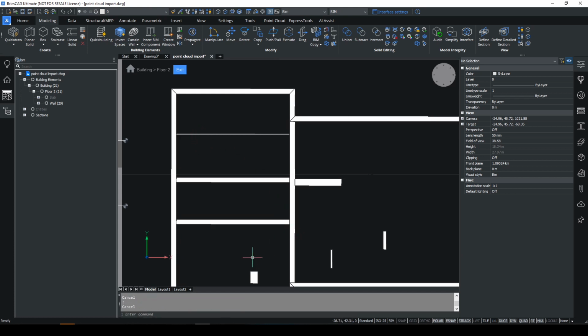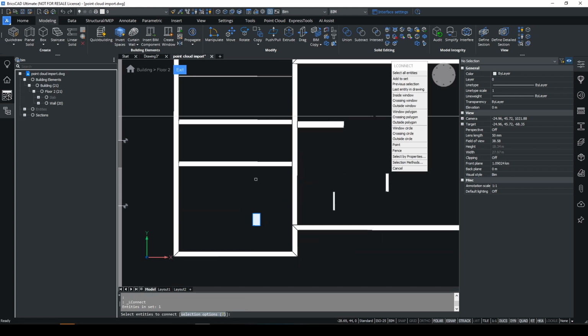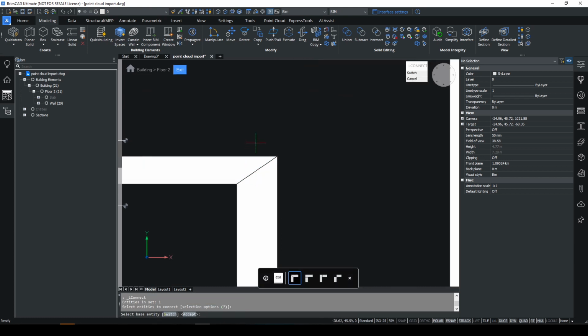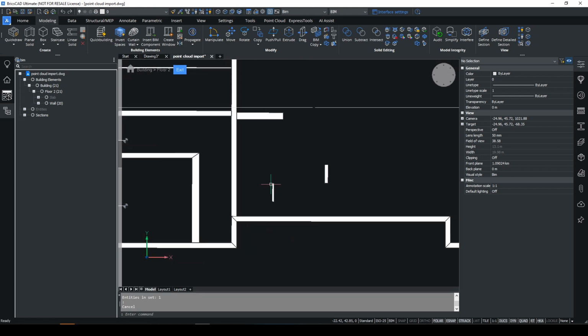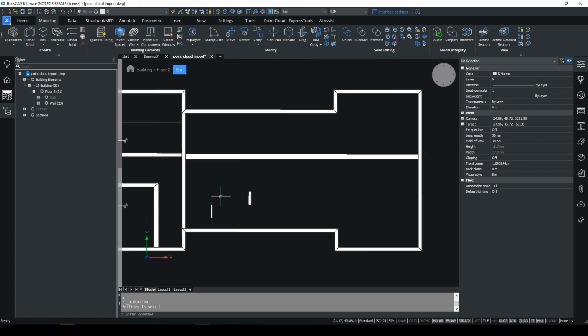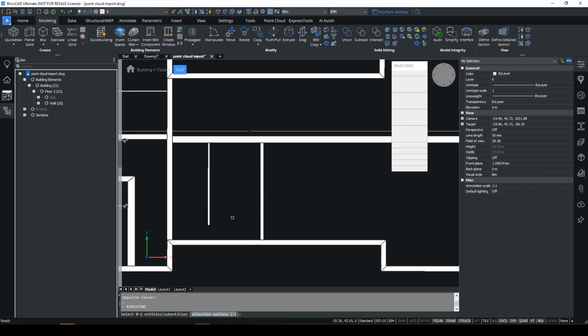You can obviously also use the other commands, such as the L-connect command. So we connect this wall to this wall here, pick the version we need for the actual corner piece by pressing Control, press enter to finish that command. You can go for BIM extend here, etc. I'm not too worried about making this accurate at this stage. I'll just show you what the various commands do. So I'll extend this out here again. You can see how quickly you would work through this.